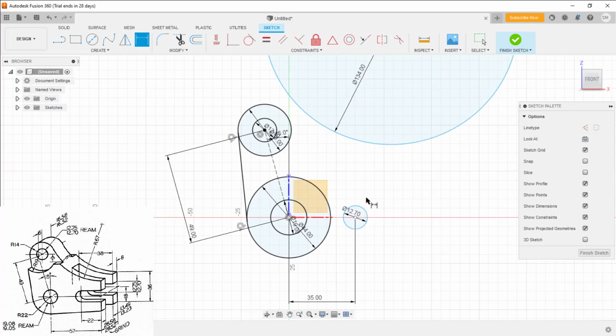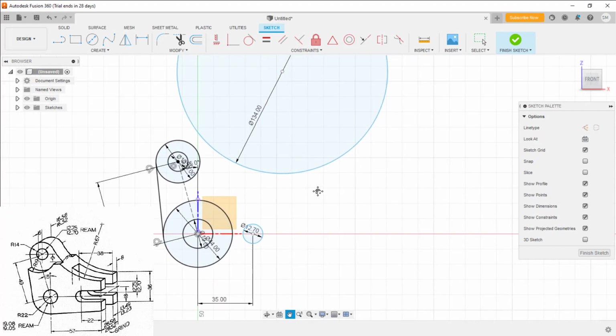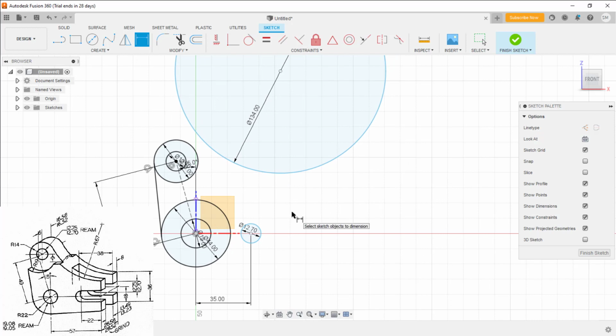Yes, now what I can do is, I need these reference lines to be created. I'll refer to the origin, drag down, and create this downward line. Again on the top, same thing, referring to the origin and this. If I refer to this as well, I need to define the values, remember that. Yeah, if I start from this side, you can easily snap the tangency. Now escape, you can define the dimension.